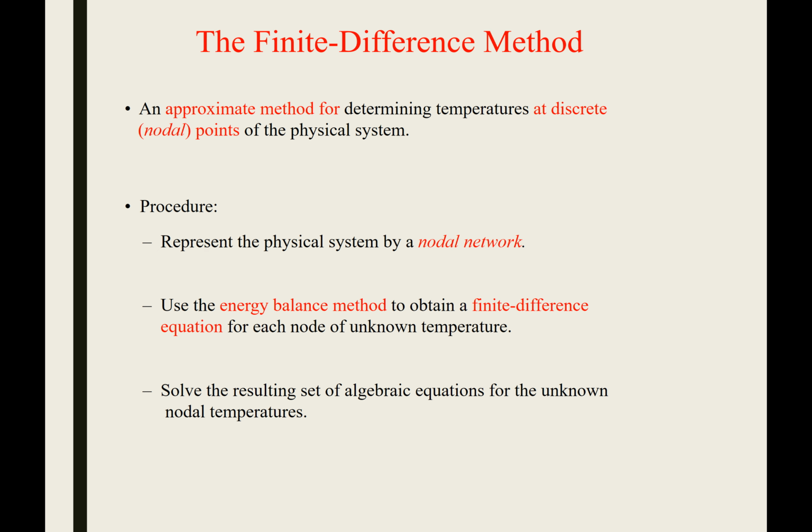So on one extreme we have trying to solve the two-dimensional form of the heat equation analytically, and that's very restrictive. Only under certain limiting assumptions can you actually get a true analytical solution, and it gets very complicated even then. Then on the other extreme, you have this shape factor or dimensionless conduction heat rate. So somewhere in the middle lies this finite difference method, or using a numerical method to solve these kind of problems. And this comes down to the same skill I've been trying to get you guys doing, is just defining a system and putting an energy balance to that system.